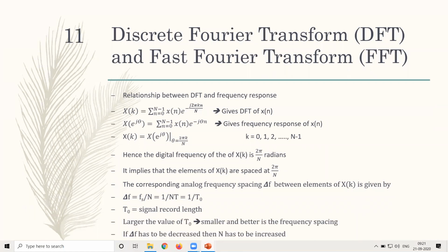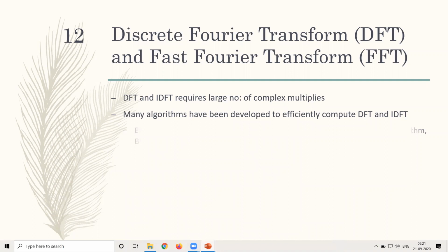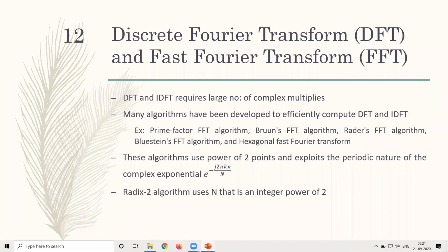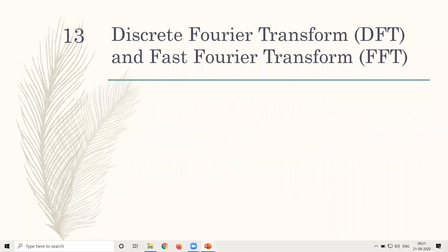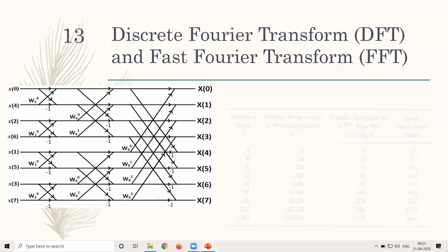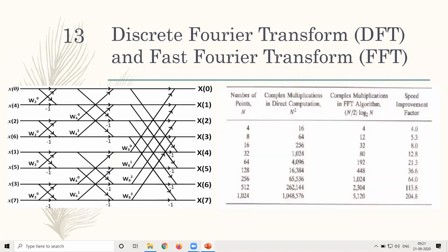So these all things we have discussed in the previous sessions, and apart from this, we discussed what is meant by FFT, and we saw a few of the comparisons related to FFT and DFT. And what are the special concepts which come into existence over here. If we observe one case, what we can see is bit reverse addressing. That is one concept which we can observe here.